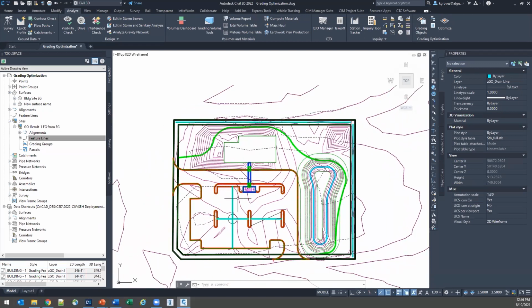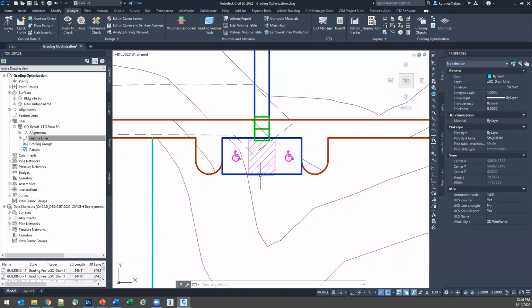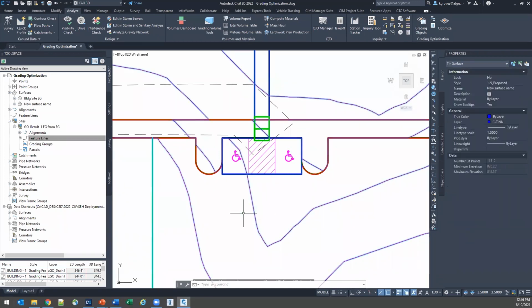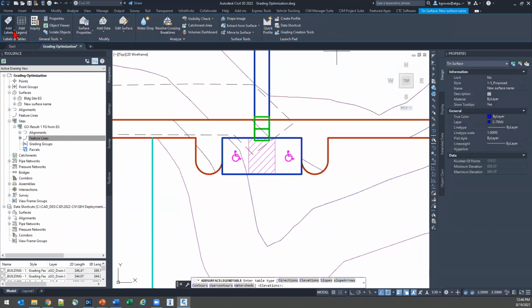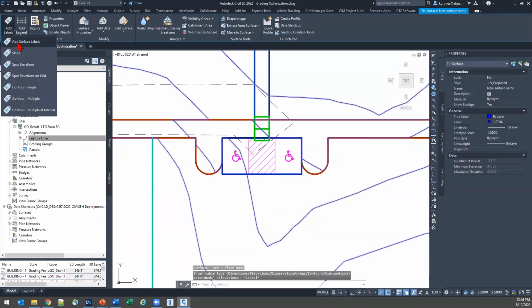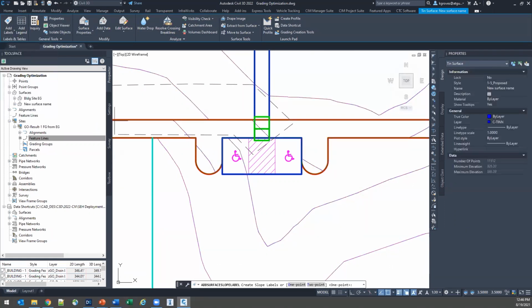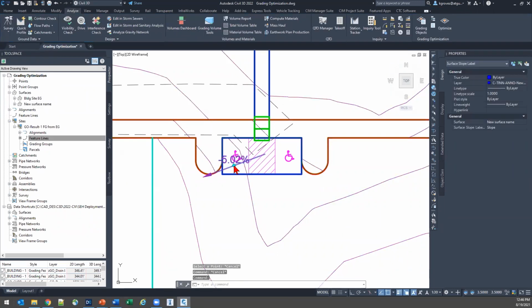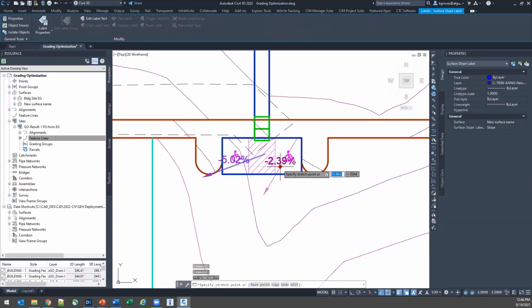So it got us close. It helped us figure out which direction we overall were trying to move in, keep some of those constraints for things like our ADA zone. If I slap down a slope 1 point, oh, that did a very poor job of giving me a 2% parking area over there.